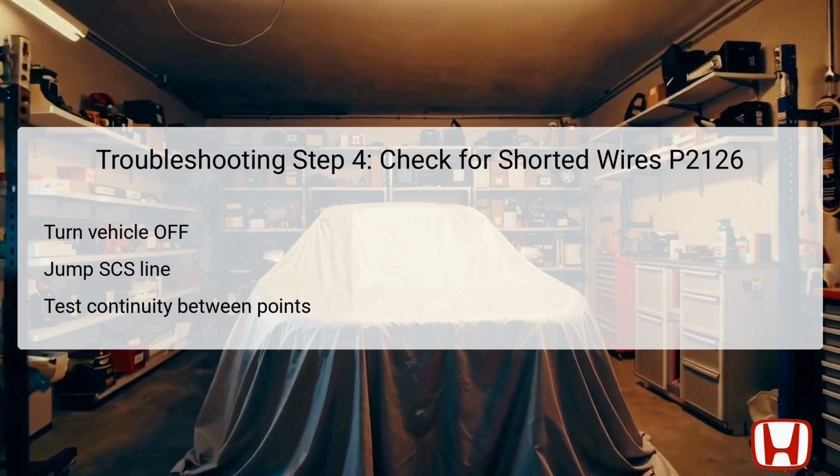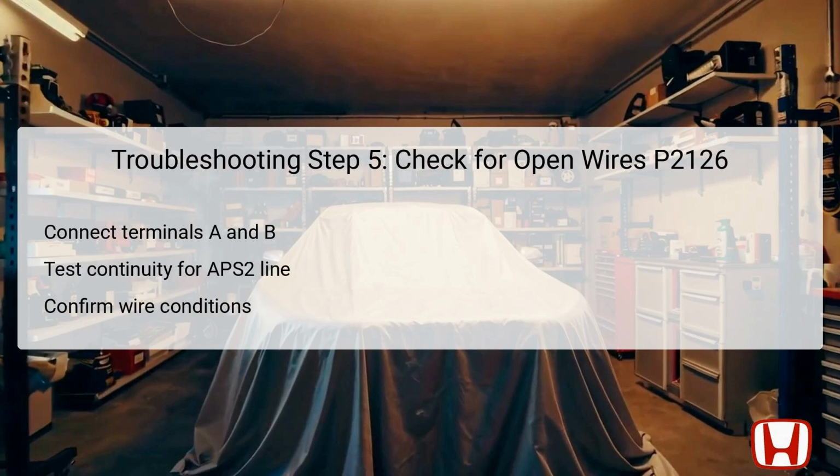If no continuity is found, the wiring appears intact, requiring you to shift focus to other diagnostic steps. In the continued effort to diagnose the P2126 code, you will need to check for open wires in the APS2 line connection. Begin by connecting terminals A and B of the APP sensor 6P with a jumper wire, grounding it appropriately. The goal is to test for continuity, monitoring whether the electrical signal can pass between designated points while the wiring remains disconnected from the APP sensor.